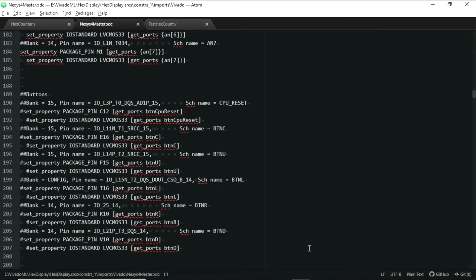And so yeah, if you don't have your XDC, especially if you're unfamiliar with FPGAs, you're not going to get anything done for a long time. You're just going to be looking at the unit and trying to determine what pin is where. And you could write a program that would access all the outputs of the FPGA and just go through them one at a time, turning them on and off.